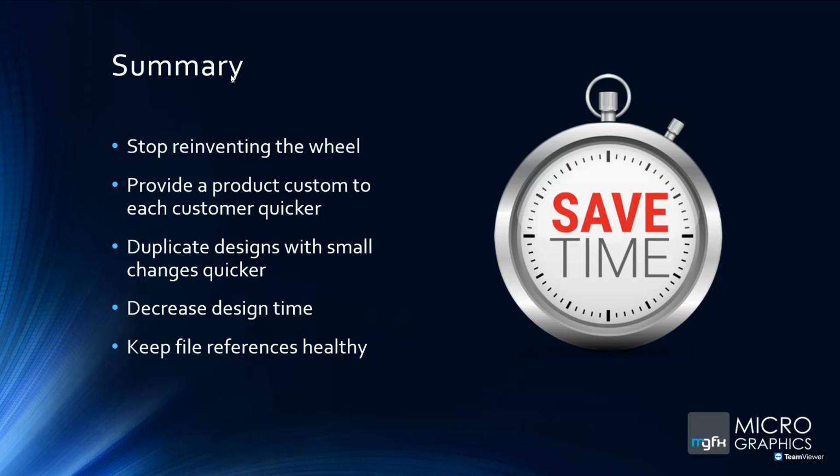And then the biggest point I think here from a designing perspective, from a management perspective, is keeping those file references healthy. Making sure that once those files are renamed, you do not get any broken links to drawings, to external files, assemblies with missing references or parts that can't be found. So yeah, that would be a quick summary on why you would want to copy design. Also went through the processes of how to copy design in the various different places.